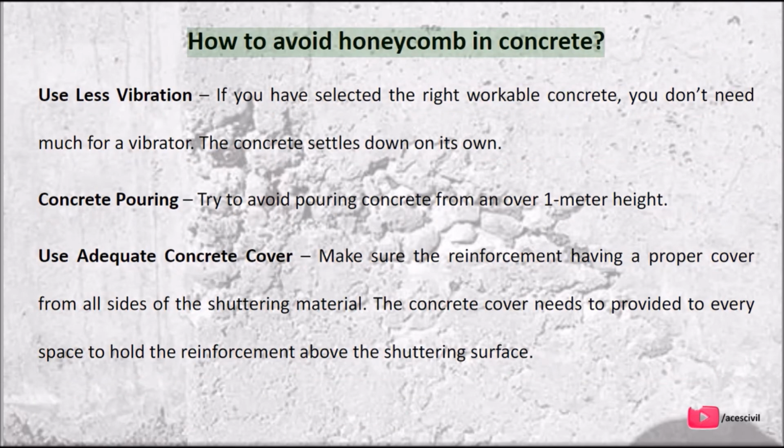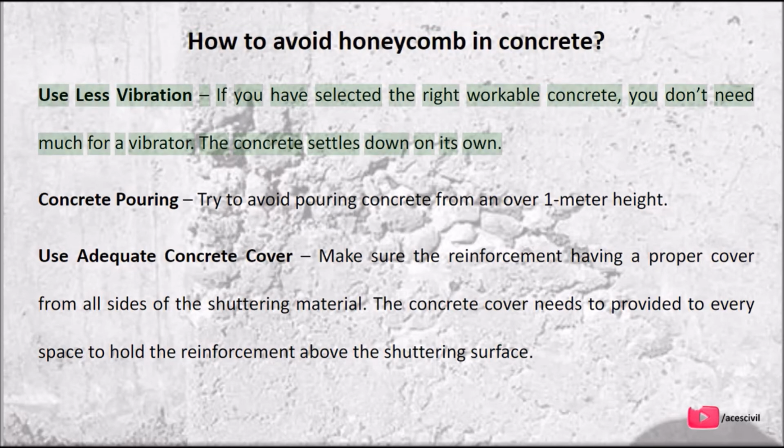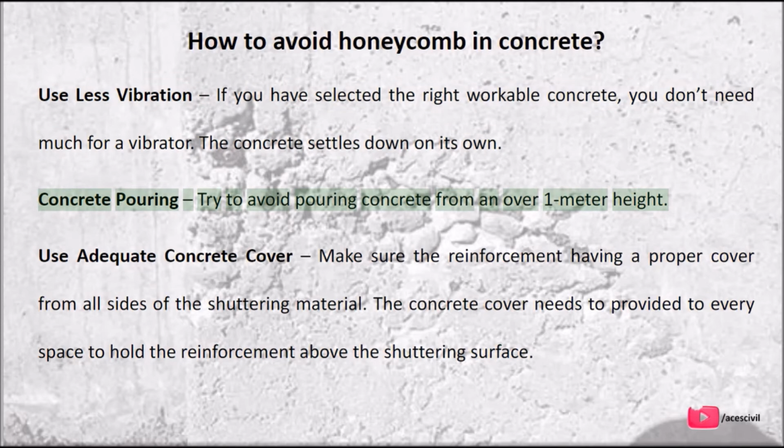How to avoid honeycomb in concrete? Use less vibration. If you have selected the right workable concrete, you don't need much of a vibrator. The concrete settles down on its own. Concrete pouring: try to avoid pouring concrete from a height over 1 meter.